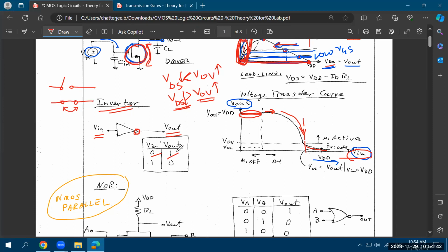A digital 1 is just a high value in terms of voltage. So you can define two levels in an analog world that, okay, I'll consider only 5 volts and 0 volts. So I'll consider only my VDD or I'll consider only the 0, right? So you can define your own logic high and logic low, depending on your circuit. So your logic low is usually the 0 volt or the ground. Logic high could be as high as your VDD.